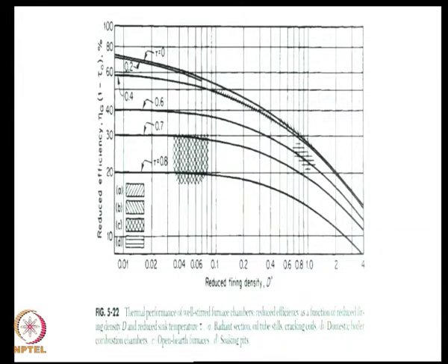If you are dealing with situations where the temperature of the sink is very high, somewhere here, this is where temperature is low, here temperature is high, like a soaking pit, there you may have to begin to worry about the second term. Okay. So, there you might want to incorporate the fact that absorptivity and emissivity are not equal.